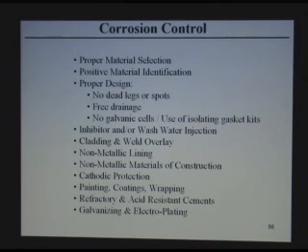If you have a very high temperature, use refractory in heaters, reaction furnaces and sulfur units. We use acid resistant cements in sulfur pits to prevent corrosion of those items. We use galvanizing for atmospheric corrosion prevention, and electroplating on some of the components of valves, etc.